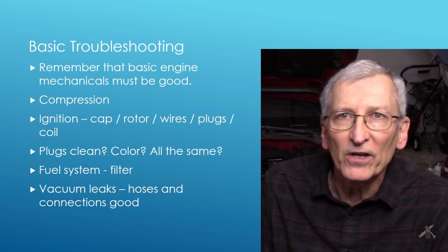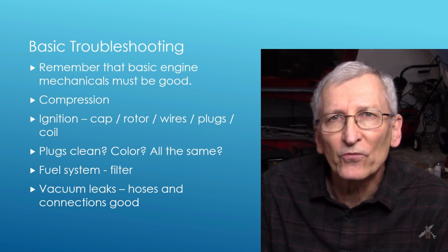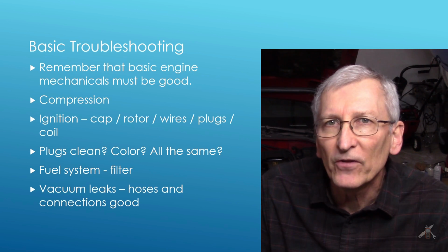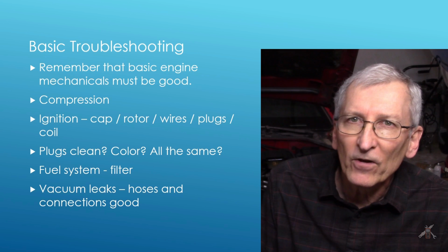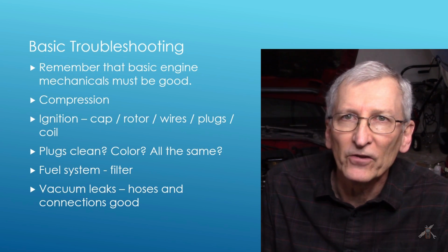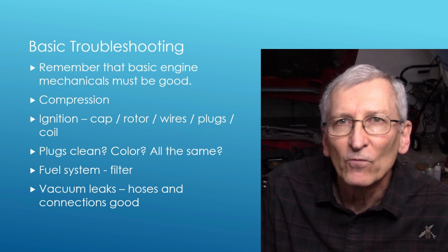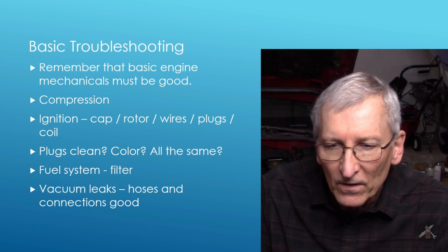And if you have to replace hoses because you find a bad one, make sure that you get something that's rated as emissions and fuel hose. There's a lot of cheap hose out there, I'm going to call it windshield washer tubing, that won't take very much in fuel fumes, and it'll deteriorate pretty rapidly. So you want something that's, like I say, rated as an emissions hose or something on that order.